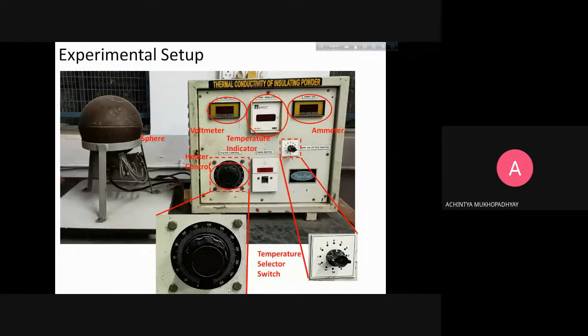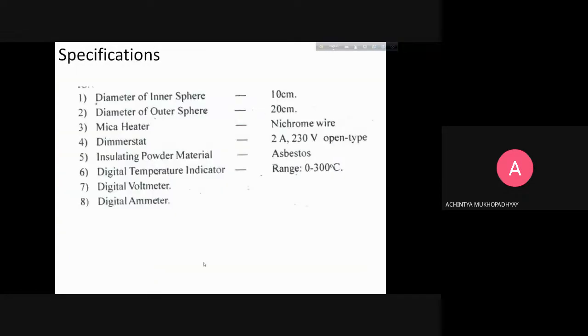So similarly here also, when you are setting the power to 20 watt, you are not using that as the power input of 20 watt. Correspondingly, whatever will be the voltage there will be a voltmeter reading here, and the corresponding current in this ammeter reading; these values are the ones which you are using in your calculations. Do you understand this? Although we are controlling it with the help of this dial, this is a control unit, we are not using these readings directly in our calculations.